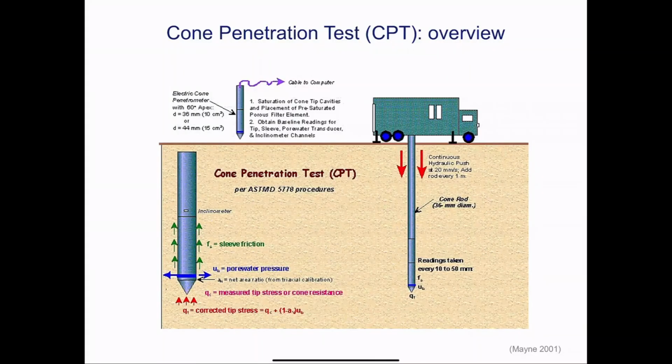All right, so let's carry on. So the next main in situ testing method I want to discuss, as I mentioned, is the cone penetration test, often referred to as CPT in engineering practice. This method is a quasi-static penetration method, as I mentioned, and mainly used for clay. Now, how does it look like?